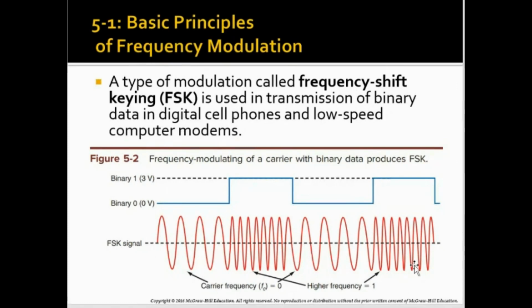What we've seen in the previous example was a form of analog modulating signal, but if your modulating signal is digital, it means there is a limited number of amplitude changes, like what we have in this example, which is binary. There are only two levels of amplitude, a low voltage and a high voltage. We have 0 volts and 3 volts, for example, and these keep changing. There is no other amplitude here.